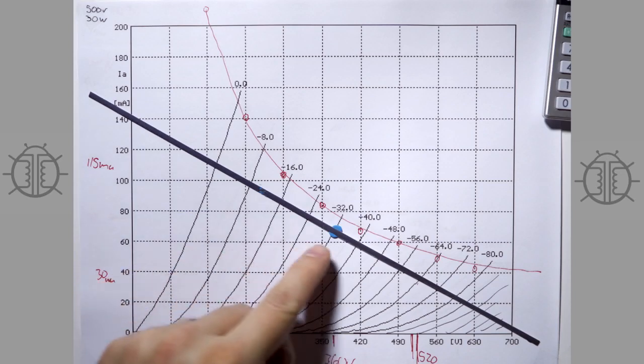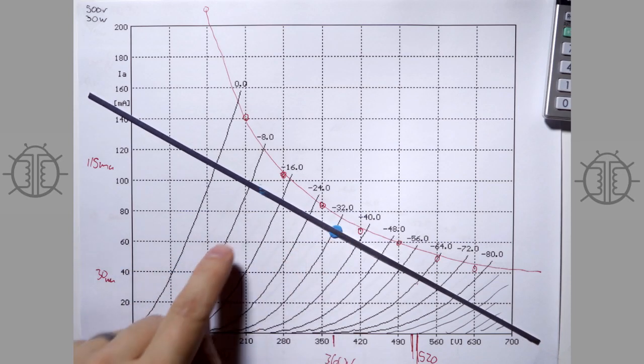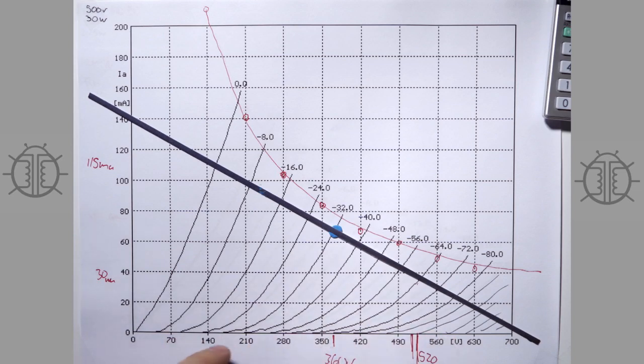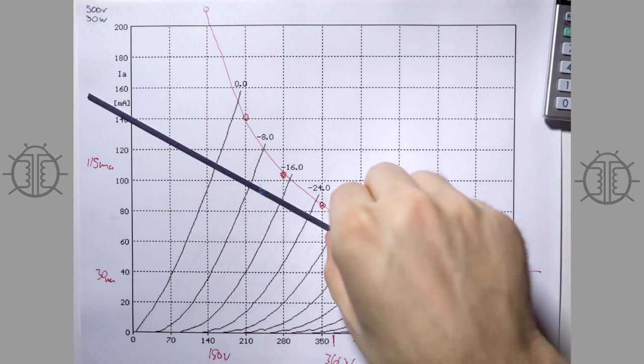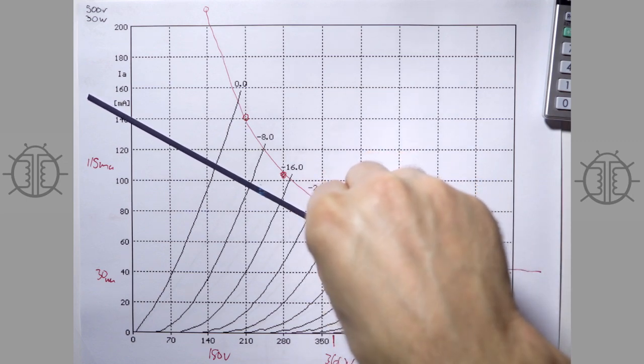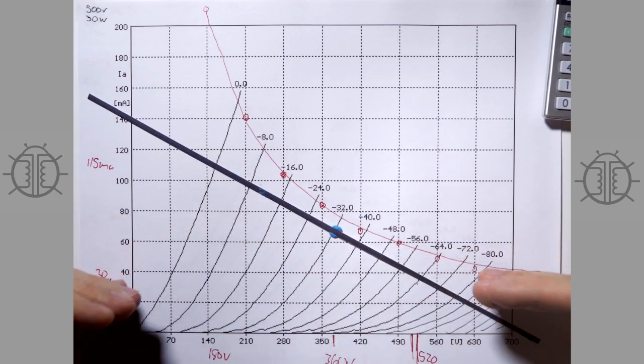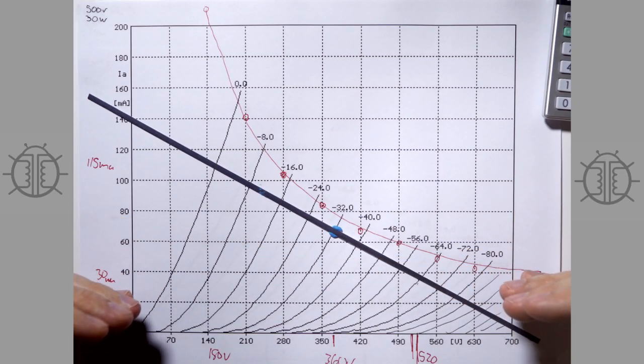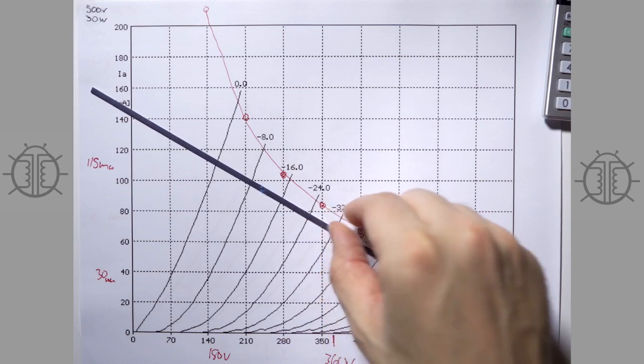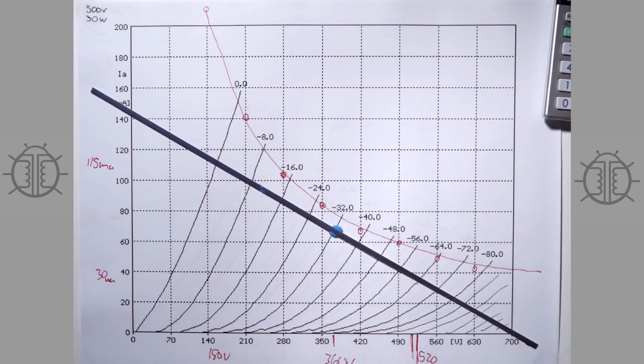All we have to do is look at the voltage we put into the grid and the voltage we get out at the plate to see what the gain is. Obviously the gain, the mu of the tube, is going to be with that theoretic infinity load line. Since we've tilted ours, our actual gain will be less, and that's normal.